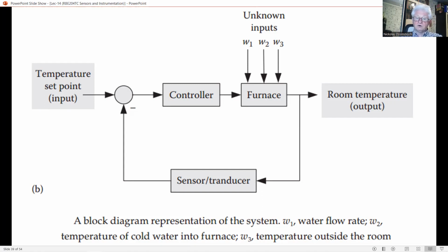With feed-forward control, information on the disturbance input from W1, W2, or W3 will be available to the controller immediately, and its effect on the system response can be anticipated, thereby speeding up the control action and also improving the response accuracy. Faster action and improved accuracy are two very desirable effects of feed-forward control.